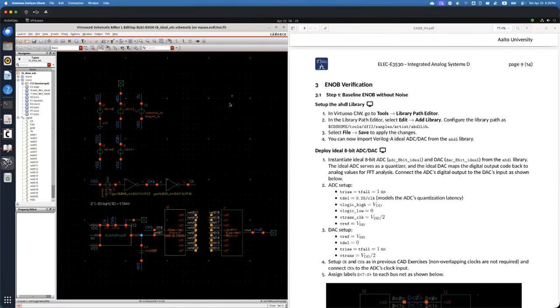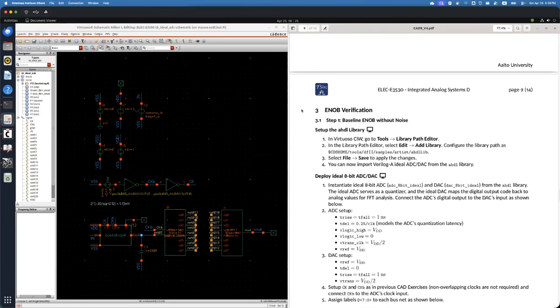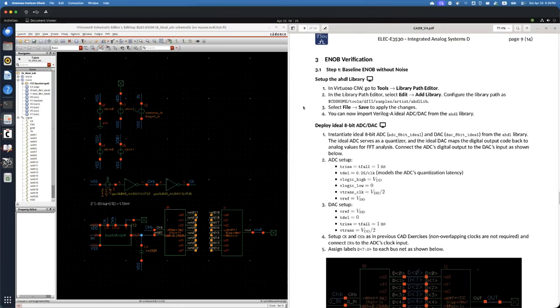Welcome to this video, and let me continue from our previous discussion about our CAD exercise 9. It will be about ENOB verification, effective number of bits for ADC. So the first step will be the baseline ENOB without noise. We will verify, as a baseline, our ideal ADC using a Verilog-A model.